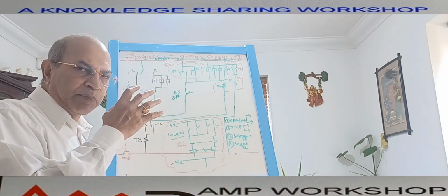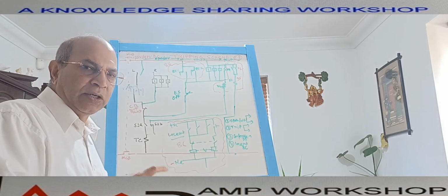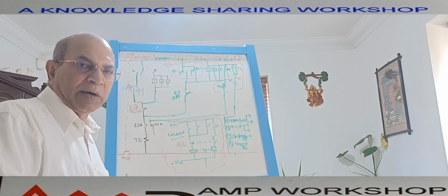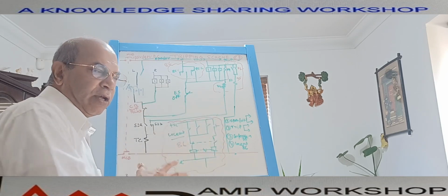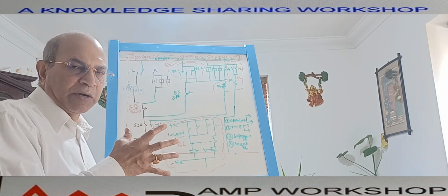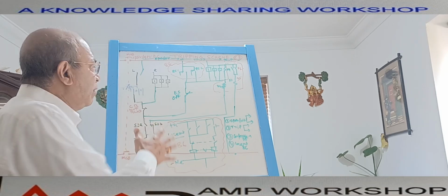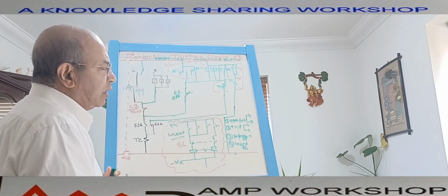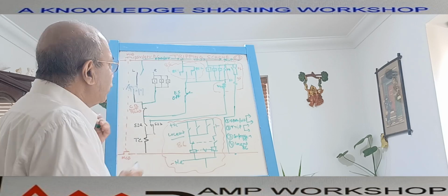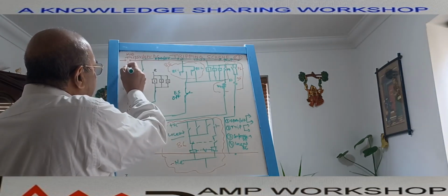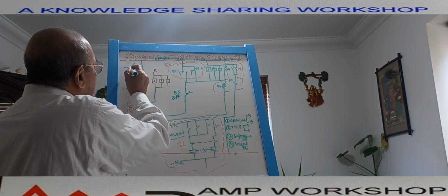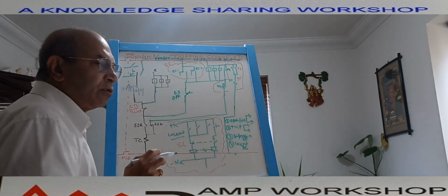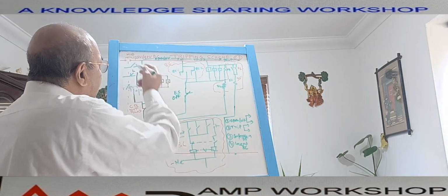So that if the power supply fails for that particular circuit, the MCB auxiliary contact can be used for indication or alarm purposes. As the tripping circuit is also a special part of the circuit breaker control schematic, we have given it a separate dedicated MCB to get the power supply to this panel from the main DC. This MCB has an auxiliary contact that I have not shown here. That auxiliary contact could be NO or NC, and we can use it for alarm indication in case of failure.